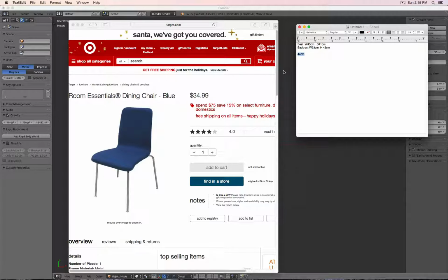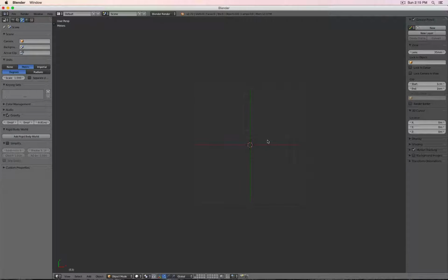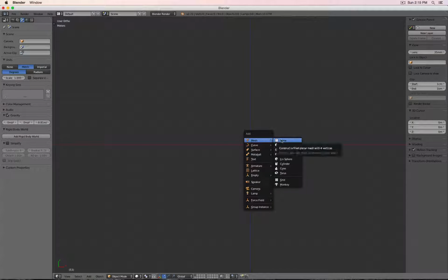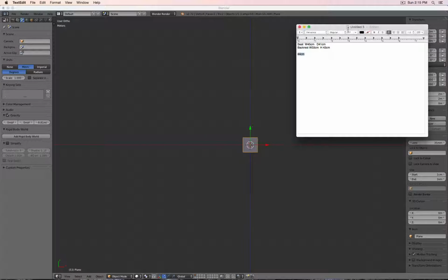So if I want to transfer that into Blender, I would approach this one differently than, for example, in a solid modeler with dimension or sketch dimensions. I would simply create a flat shell and then bend the shell into the shape I need. So that means I, for example, start with a basic plane, 45 centimeters wide and 41 centimeters deep.